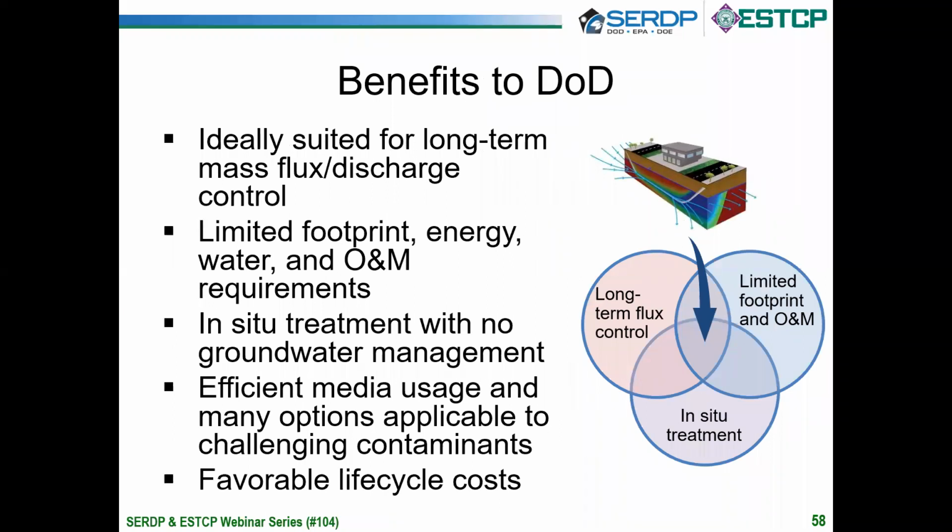So the benefits of the HRX well: it's ideally suited for long-term mass flux or discharge control. It has limited footprint, energy, and O&M requirements. It's an in-situ treatment technology with no above-ground water management. Media usage is efficient, and there are many options applicable to challenging contaminants like chlorinated solvents and even PFAS. And based on this demonstration project, the life cycle costs are quite favorable in many applications.